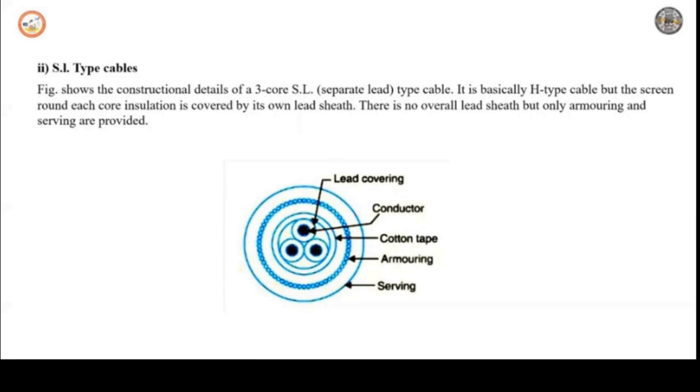When the load on the cable decreases, it cools down and there is contraction of the lead sheath. Due to this, air may be drawn into the cable forming voids. This deteriorates the cable insulation. Next, moisture may be drawn in along with the air, which deteriorates the dielectric strength of the dielectric. Mechanical shock can cause voids. The breakdown strength of voids is much less than insulation. Hence, voids can cause permanent damage to the cables. This is a brief discussion about these two cables.